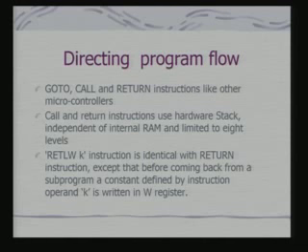If you see these program flow control instructions, goto, call and return, the call and return instructions obviously use the hardware stack, which is independent of the internal RAM, and it is limited to 8 levels. So even in a hypothetical scenario where you assume there are no external interrupts, you still cannot have arbitrary nesting of subroutine calls, because your maximum depth is fixed.